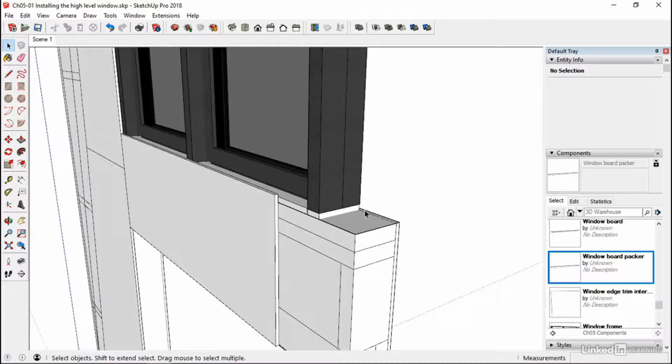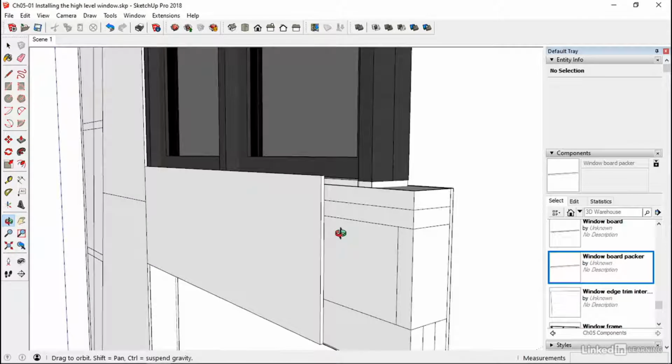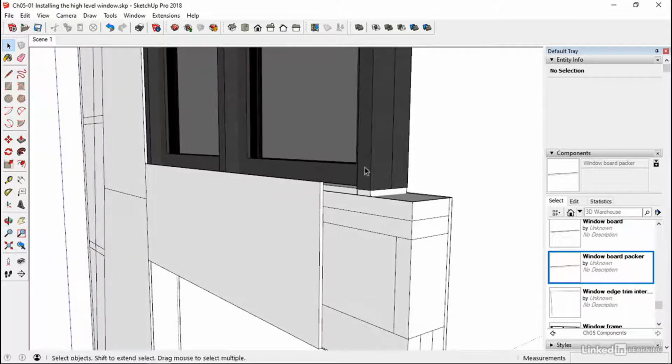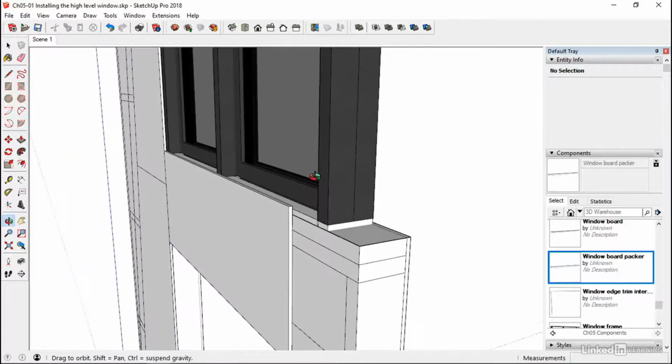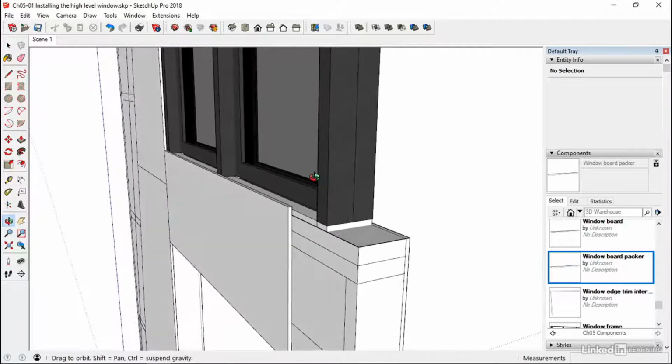Most things in building cover something else up, so ultimately you'll end up with a trim or something nice. The details considered on this are shadow gaps a lot of the time, so a little bit more care has to be taken when we're putting all this stuff together, as opposed to just plonking a piece of timber over these gaps, hiding them all, and potentially having drafts or not very well detailed trim.